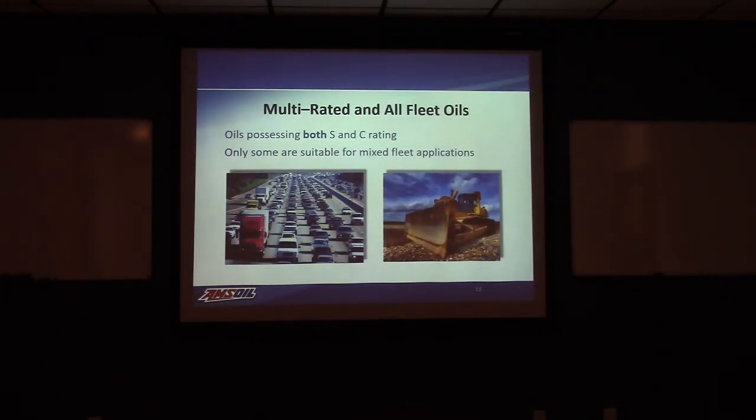One of the things that you can run into is oils that have both an S performance category listed on it and a C. Well, that would certainly indicate it can be used in both applications. In many cases that is true. There are a lot of all-fleet or mixed-fleet oils out there that are used in applications where a company has both gasoline engines and diesel engines.